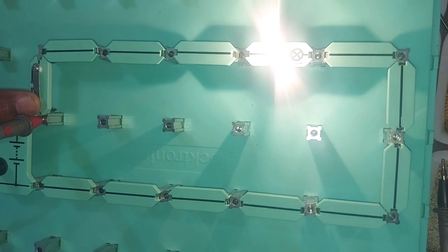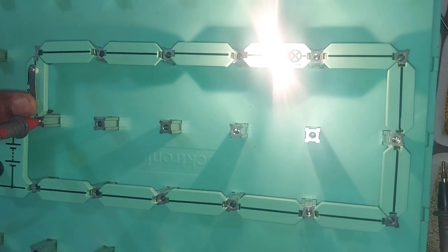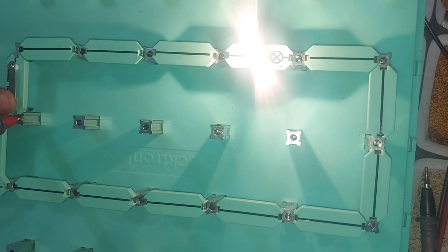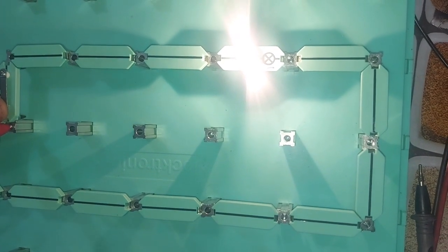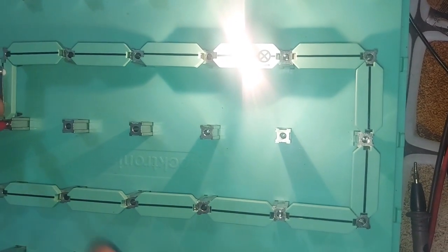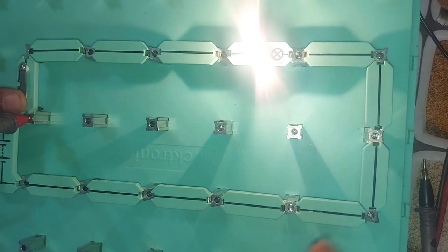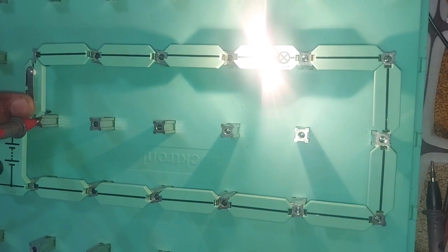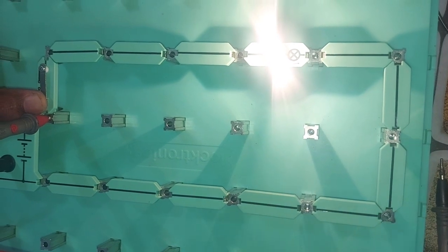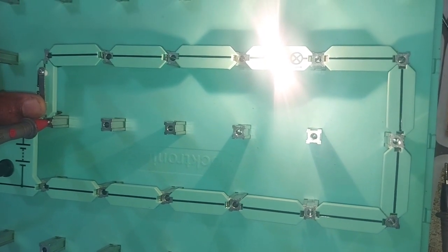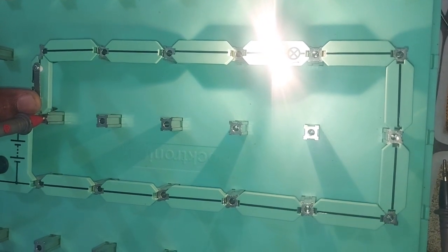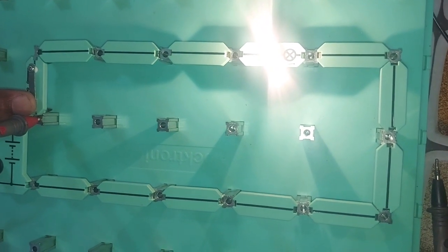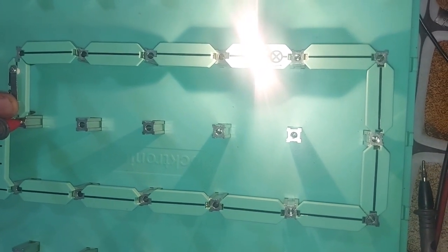These are the things that can set you apart from another technician, because when you have this kind of knowledge, you know straight away, this is how I check an open. So you go for an open, you check quickly on the positive side, check on the ground side, bang, there is my open. And then you confirm straight to the boss, there's an open on the ground side. How did you know within just a few minutes? These are the skills, guys. I know people say, oh, electronics takes long. Yeah, it does sometimes. But when we equip ourselves with this kind of knowledge, we will never go wrong.